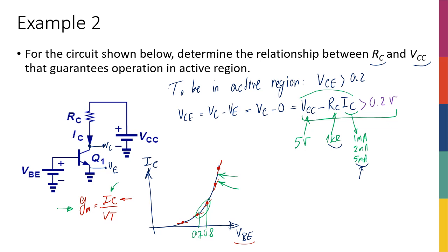You still have the power problem, but later on you will see that you're not going to get a better gain out of this transistor, because if you go back and look at the example that we calculated, you will see that the gain of this transistor is actually GM times RC. And there's a negative involved as well, by the way. All of the things that I'm talking about from this point forward in this slide is something that I'm going to discuss in the next chapter. I'm just giving you a little bit of a sneak peek, right?